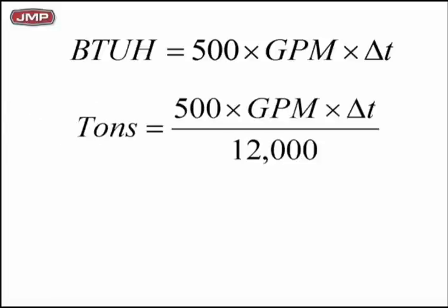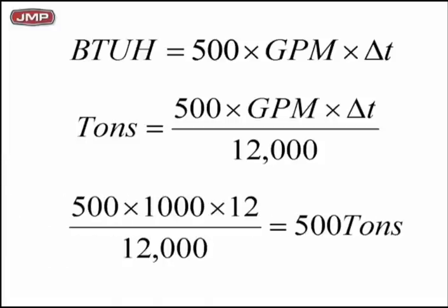Now, if I look at my chillers and I put my GPM in a ton being 12,000 BTUs, and if I had a 500-ton chiller at 12-degree delta T, my flow rate's 1,000 GPM. So I like looking at this because 12-degree delta T on chill water is a good design. Nothing wrong with it. It's 2 GPM per ton. It's a great design. And it makes the numbers simple for what we're doing.